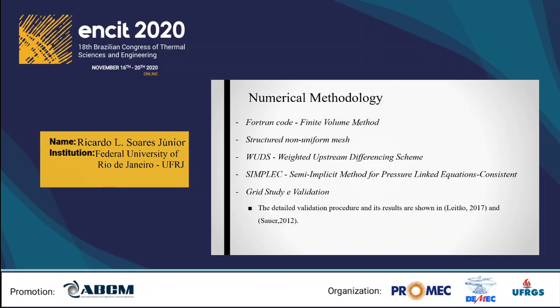A Fortran code was developed in order to obtain the numerical results. The finite volume method was used to discretize the governing equations with a collocated grid arrangement, and the weighted upstream differencing scheme interpolation is used in a structured mesh. The grid is numerically generated by the solution of a partial differential equation. The SIMPLEC algorithm is employed to address the pressure-velocity coupling.